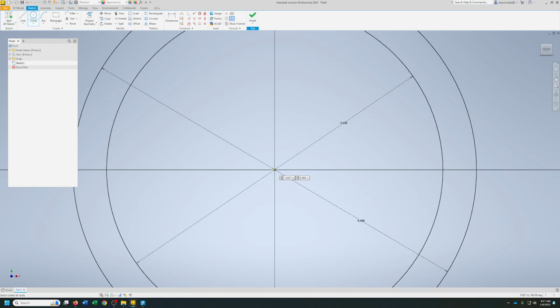All right, then we got our thing in the middle. And that one's going to be a diameter of 1.25, and it's going to have a rectangle up top. All right, and this thing is 0.25 by 0.125. 0.25 is this direction, 0.125 that direction. So 0.25, and then we'll of course center it. 0.125, and now I can trim here in there. Now we want this dimension to be 0.125, and there we go, and that's it.